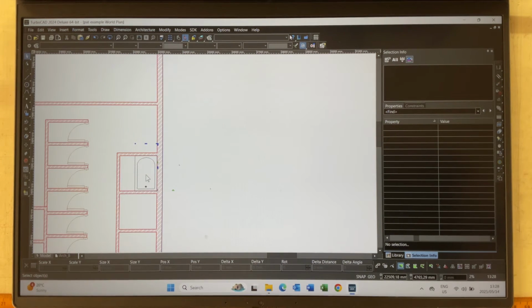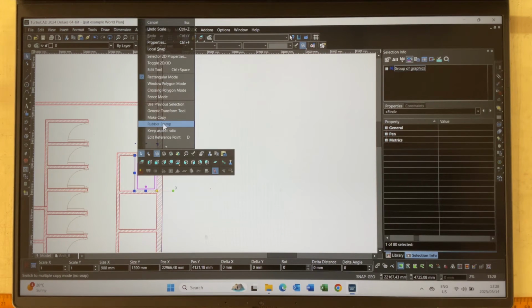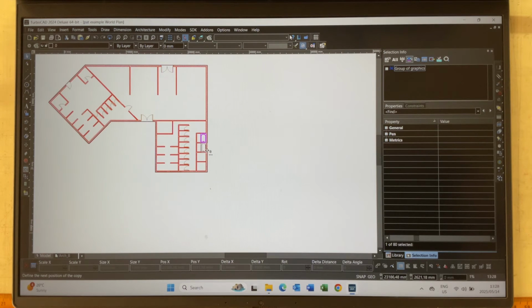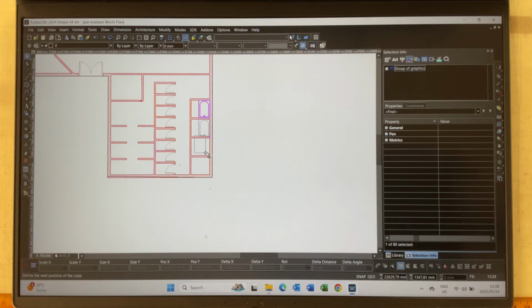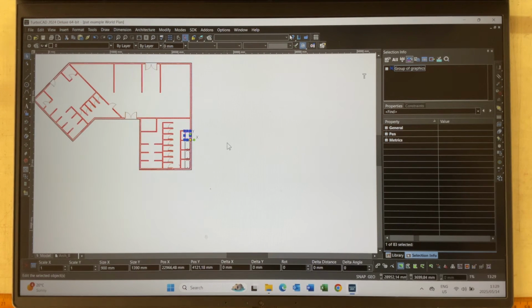And what I'm going to do is click on that and make a rubber stamp. And I'm going to click that into that room over there. There we go. Click it into that room over there. Just make sure that it's clicking to the right spot. There we go, and again to there, and I've got my baths inserted. Press escape, and I can now go, okay, I'm wanting a toilet to be put in.